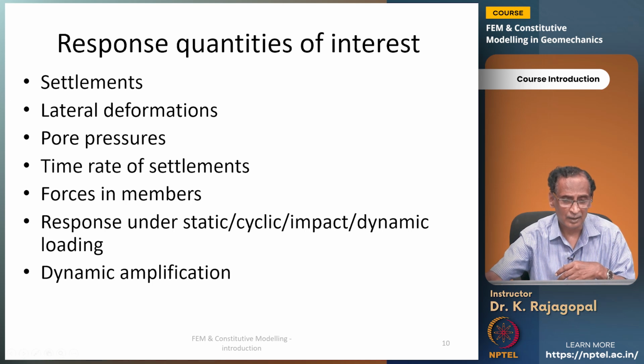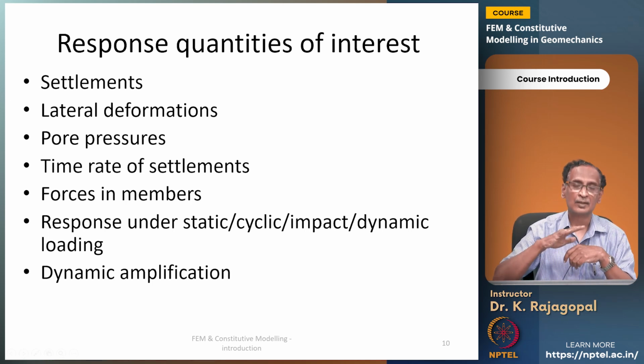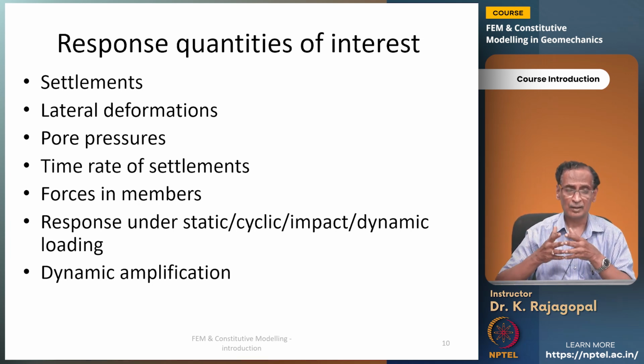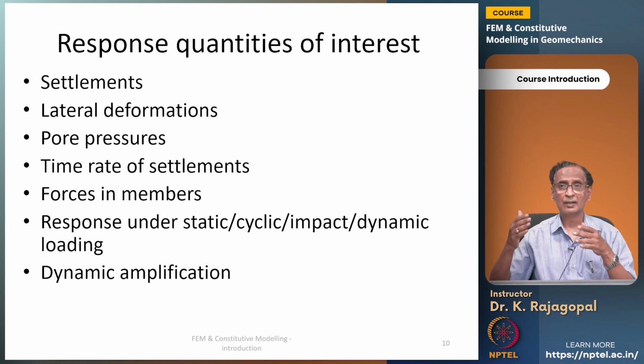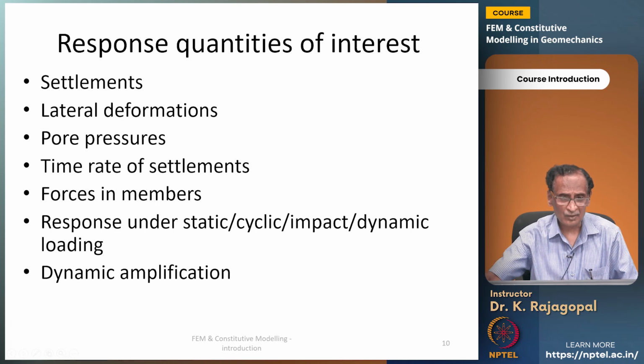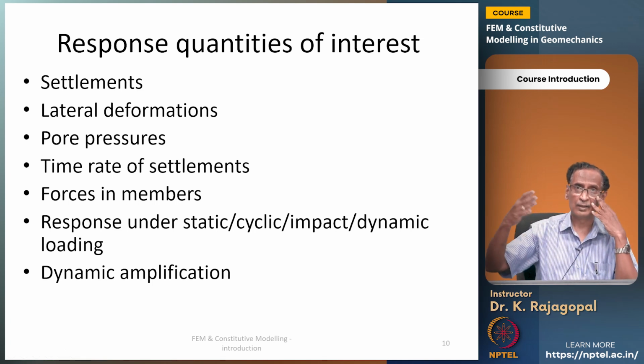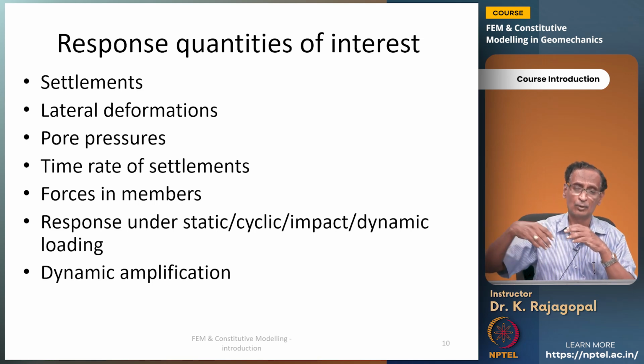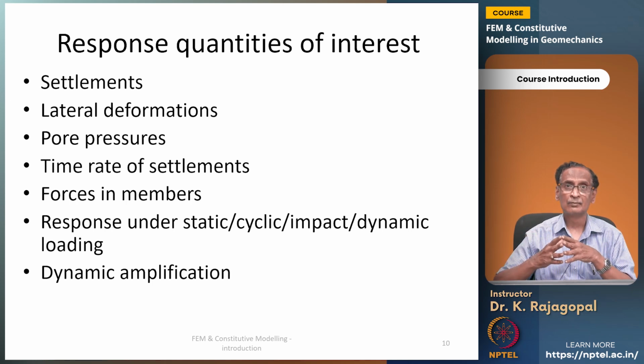Then what are the forces in the members, either a reinforcement layer or a sheet pile wall or your anchor. What are the forces that are developed that need to be accounted for in the design. Then we should be able to get the response under static loading or cyclic loading, where the load is repeated a number of times, and then impact loading, a suddenly applied load, or dynamic loading, a harmonic loading, or a seismic loading.